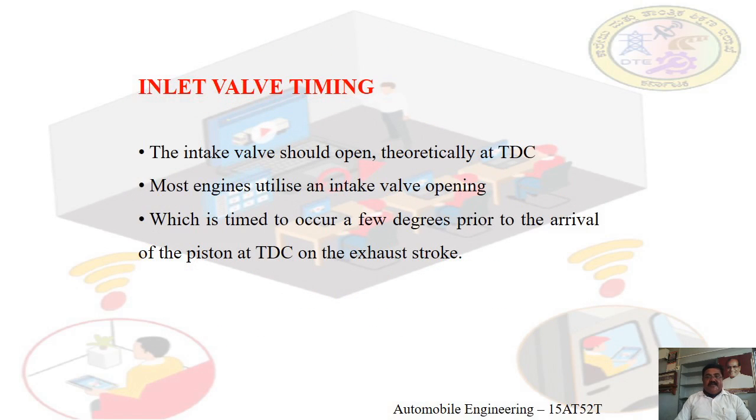Inlet valve timing. The intake valve should open theoretically. Theoretically means as per the valve timing diagram, at top dead center.